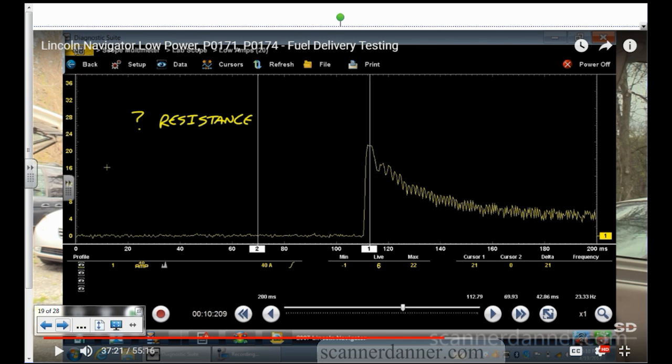The problem was a bad block ground. It was making the control side of the relay buzz. And what was it doing to the load side? Making the load side switch on and off, on and off, on and off. And it blew the circuit fuse. Why would it do that? Because that initial turn on of that DC electric motor, look how high the amperage is. This is a 22 amp peak. 22 amps of current flow.